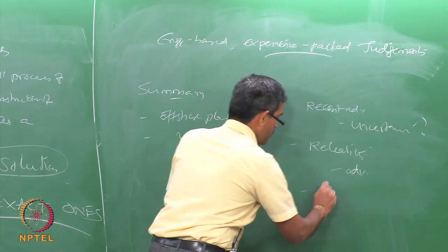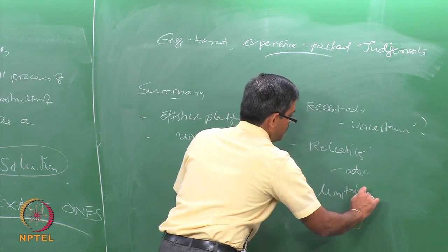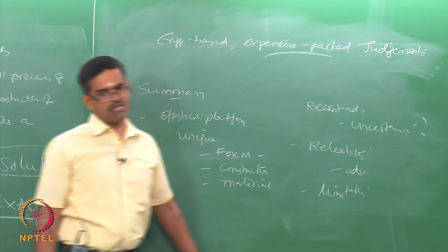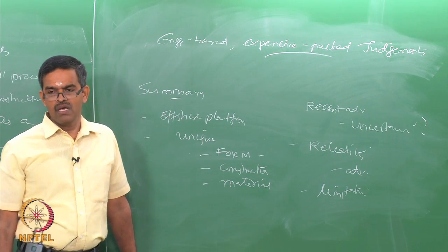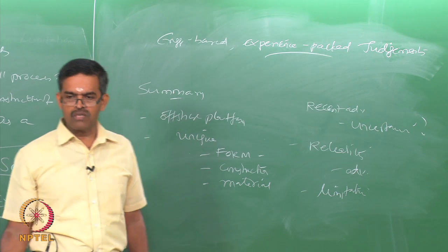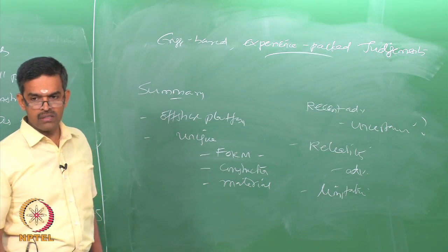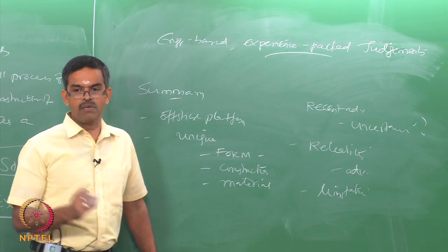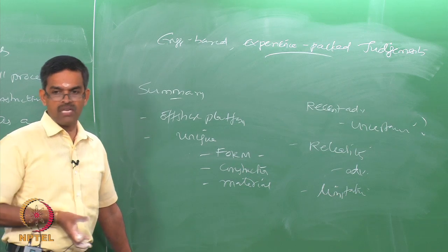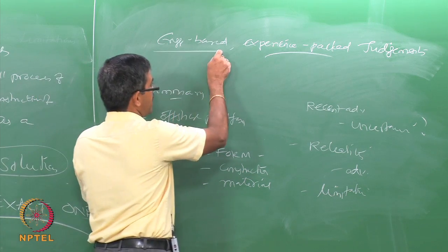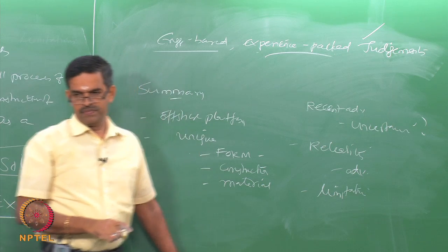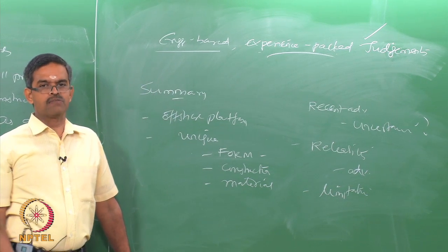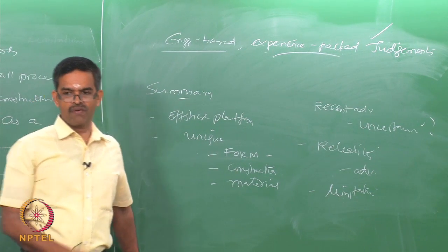But of course, we also saw serious limitations of this method, which ultimately tells me the solution given by reliability theory cannot be blindly applied on a structural system, but it requires a support, a recommendation which is purely driven by engineering based, experience packed judgment, which ultimately tells me the reliability index of a given system.